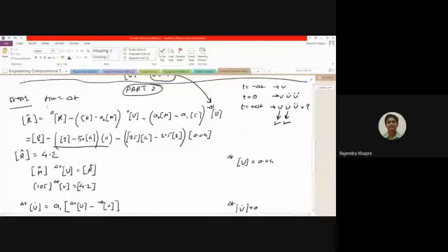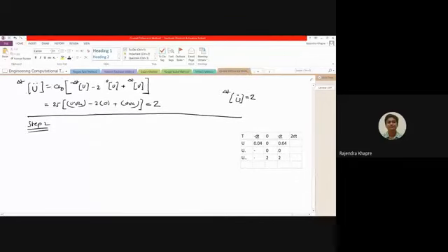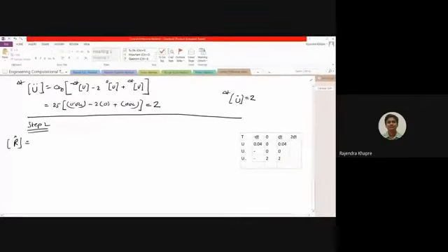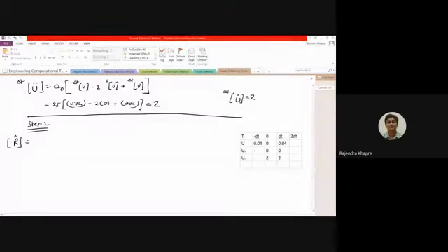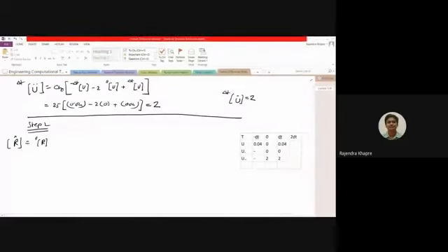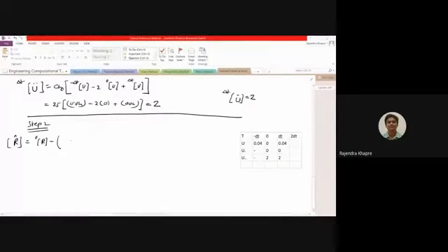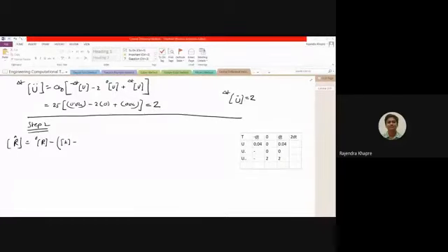what we have to do is, first of all, calculate the effective load vector R. So here the effective load vector R needs to be calculated. Let me write down an expression for this. This R can be calculated as the load vector R at t equal to 0, then minus the K matrix, then minus A2 into M, that is the mass matrix, multiplied by u, where the time is now increased by delta t.